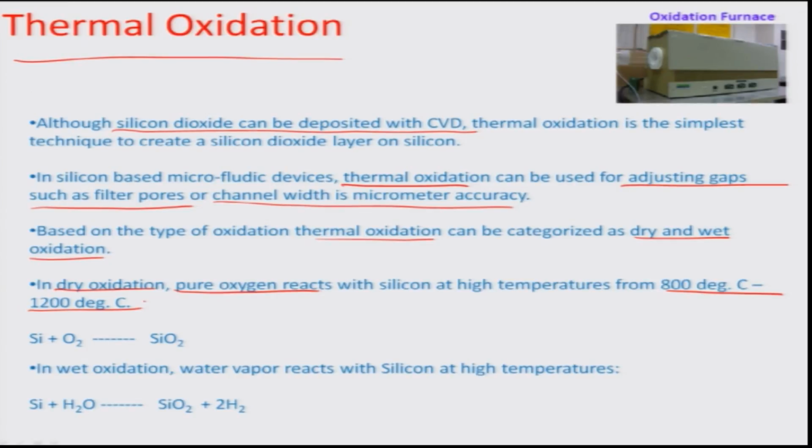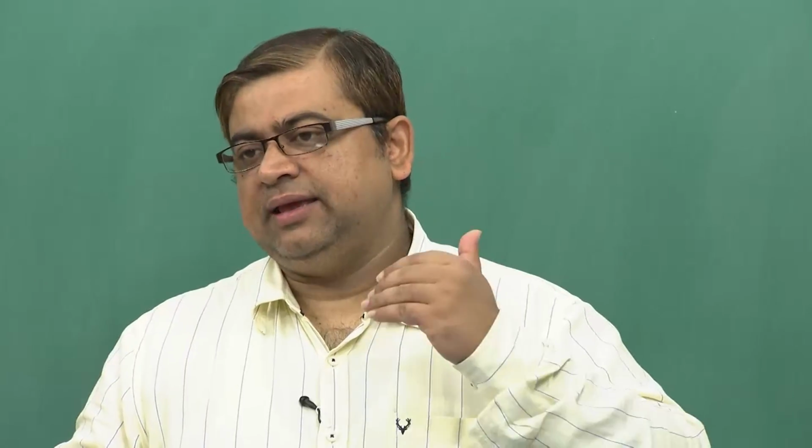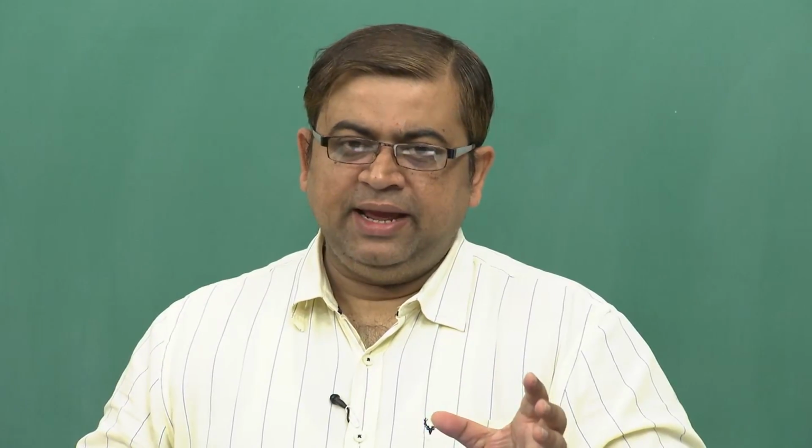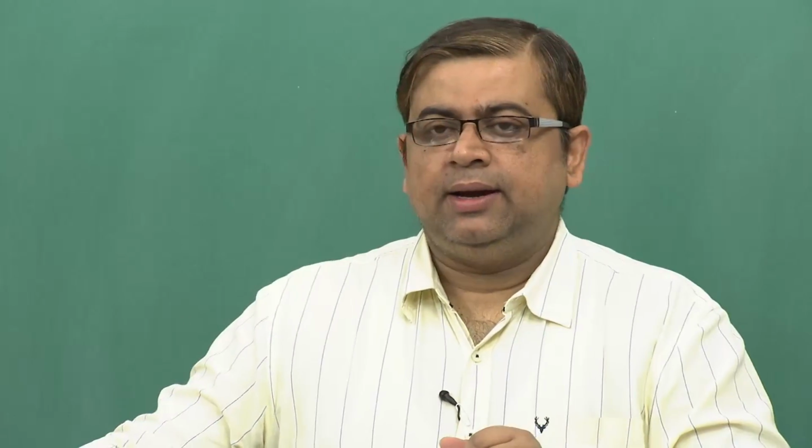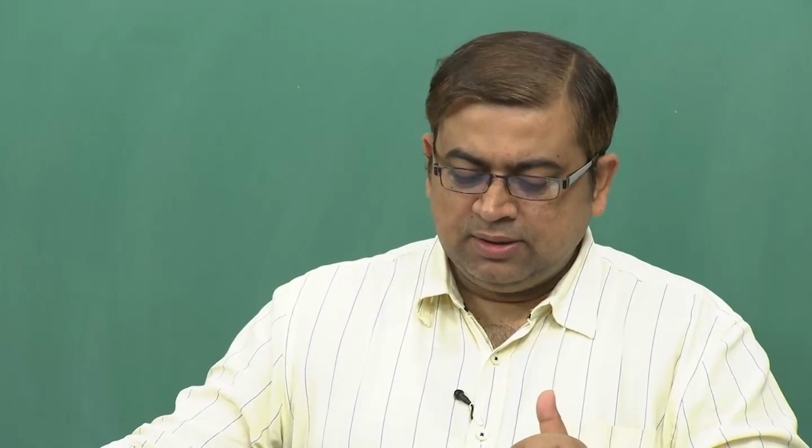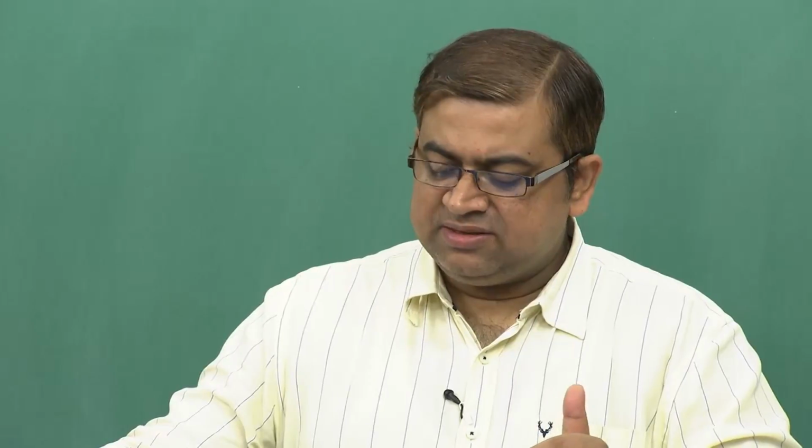And so these quartz tubes are used as stackers for the wafers, which are loaded onto a boat, again made of quartz, and the boat is laid inside the tube, and the tube closed. There is a circulation of oxygen happening in the tube from some source at the back, so that gives you the basis of the oxidation.